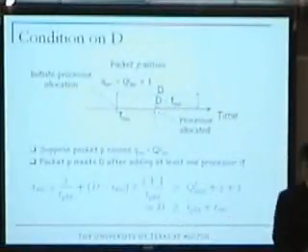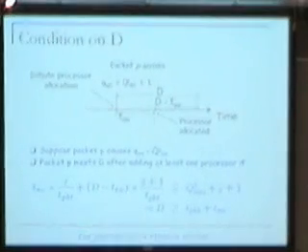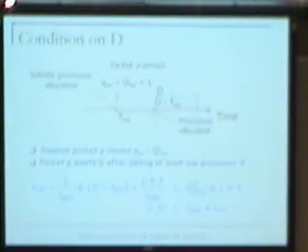Right? T switch in our experiment was 2 milliseconds, and t packet was less than 100 milliseconds. So I chose a d value of 2.1 milliseconds to ensure that there is a design point which I'm picking. Okay.